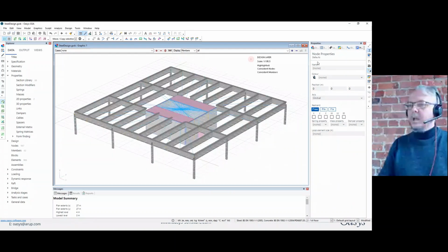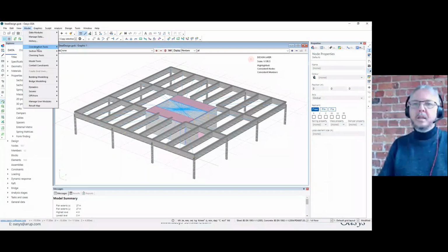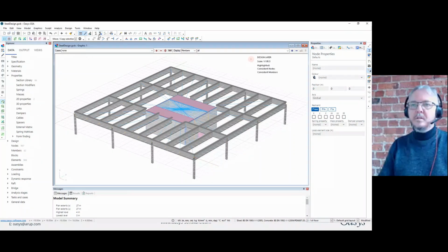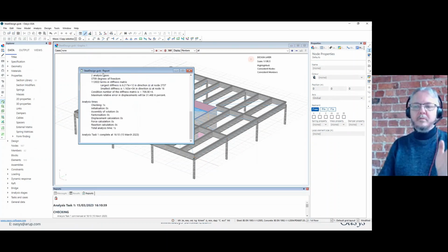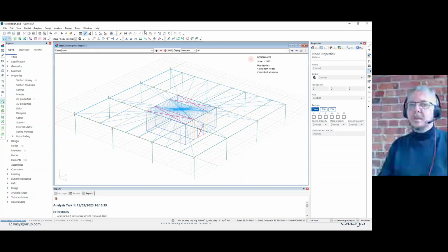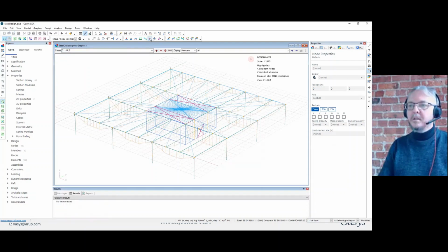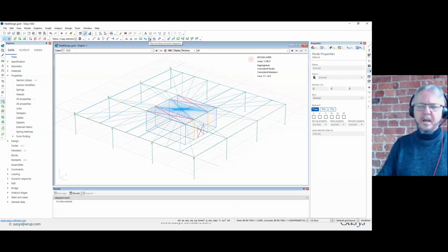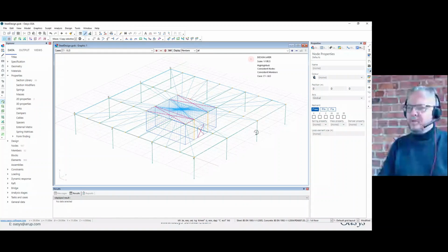So at the moment everything is very chunky. To update the elements from members, run the analysis, all is set up, ready to go. So here on design layer, and then once again we do have all the bending moments and so on. So design of these sections. Now I put all these top beams into group 1.